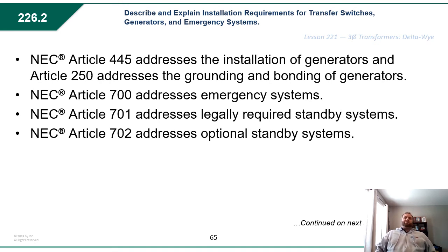The NEC articles for emergency systems, legally required standby systems, optional standby systems, just general generator information are found here. I'd write these code references down. You will probably see one of these on the test, one or two even.